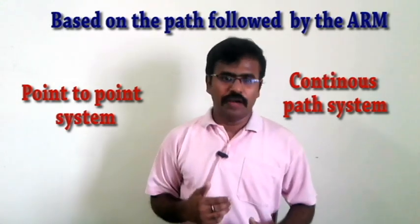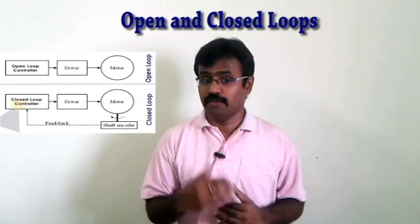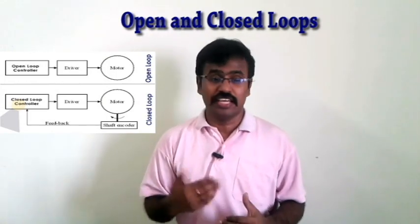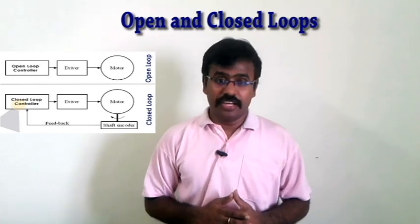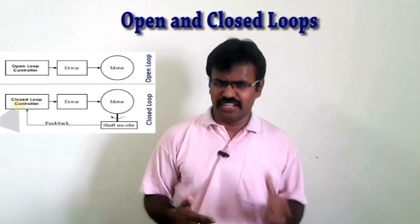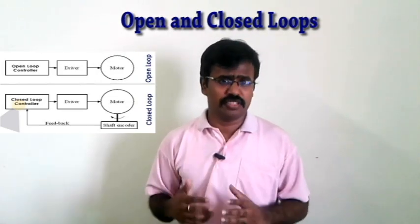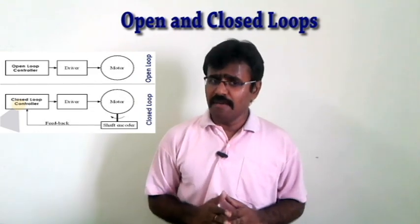Next is the open loop control system. In this case, control is given to the individual axis and there is no feedback obtained about the position, velocity, etc. In this figure, you can see the control unit, driver and a motor. In general, all the relative motions are obtained by motors. The data for the position of the motor is not obtained. An example is a pick and place robot without feedback.